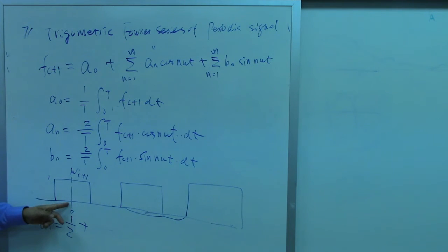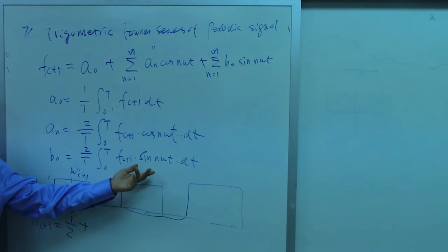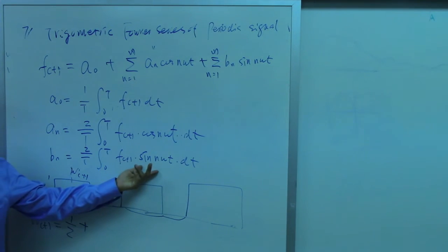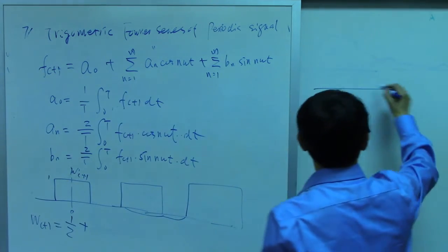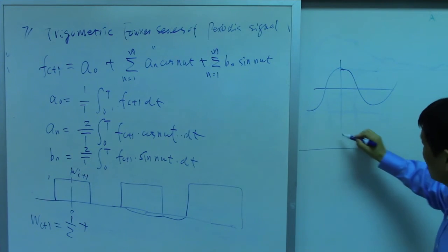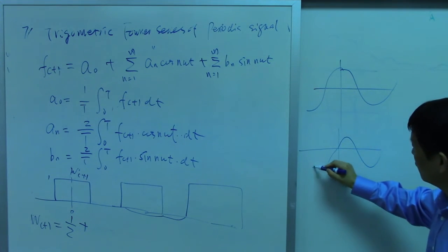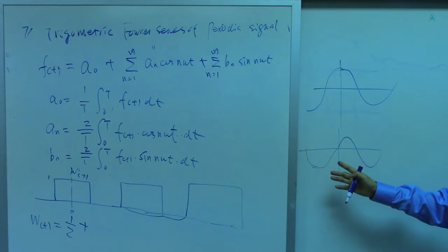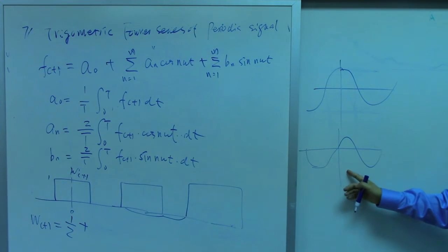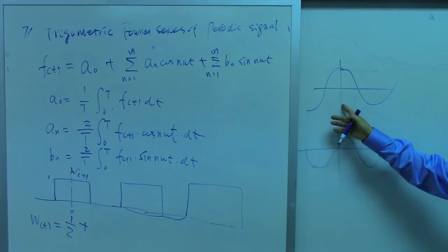If we start the origin, the start time, right in here, we know this signal is symmetric. You can see this one flipping this way, they are symmetric. If the signal is symmetric, that means we don't have any sine function, because this is an even function, an even signal. Sine function is odd, right? So the cosine function looks like this. See, they are even. They are symmetric. But the sine function, like this, look at this signal. They are anti-symmetric. So if your signal here is even, we cannot have any component like this. We can only have a signal like this. Right? Yes, it is correct.